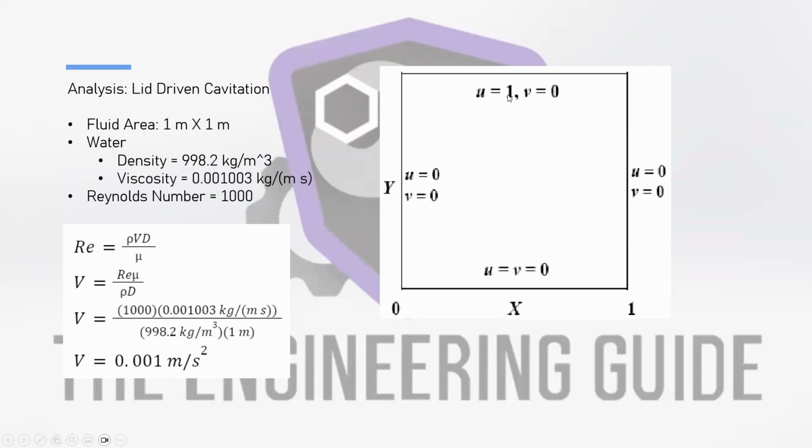And our top wall is going to simply have some velocity in the x direction and no velocity in the y direction. We are going to initialize our fluid domain, or cavity, with water, which in ANSYS has these properties: a density of 998.2 kilograms per meter cubed, and a viscosity of 0.001003 kilograms per meter second.